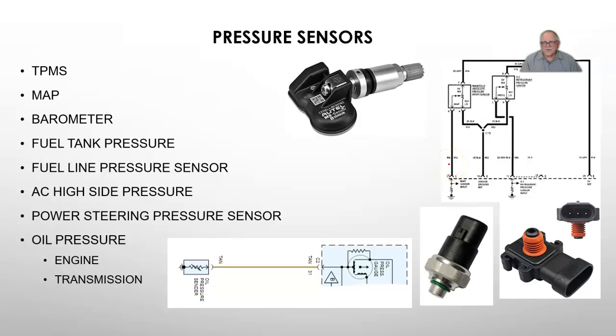When you go to diagnose it, if there's a code for the sensor, this MAP sensor, which is dealing with manifold pressure, is going to react to what's running on the car. If the engine's not running right, that can set a MAP sensor code and there's nothing wrong with the sensor. You need to check base engine first, make sure the engine is running good.